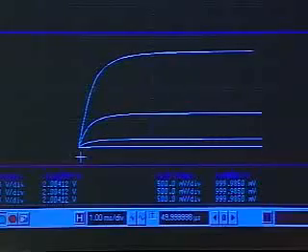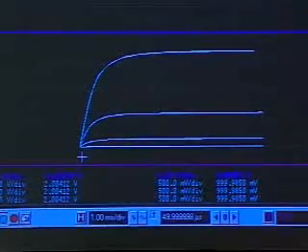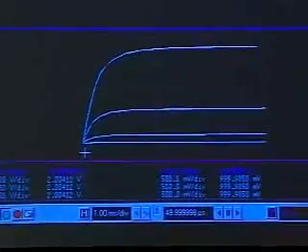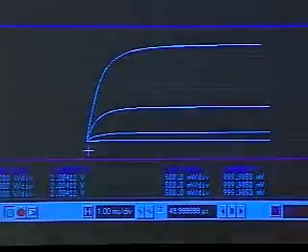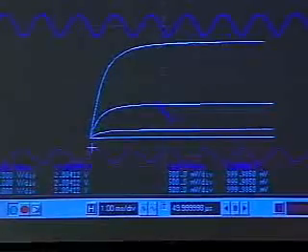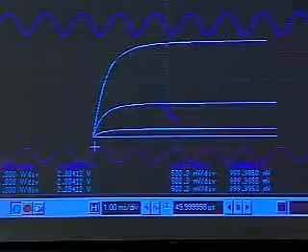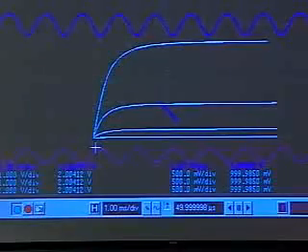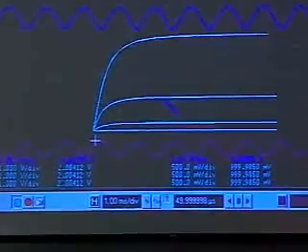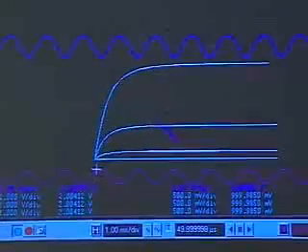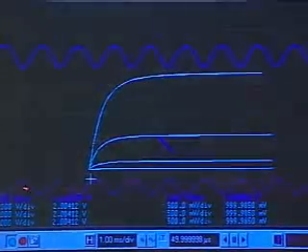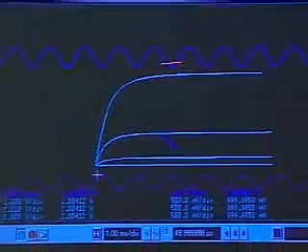Okay. So next what I'll do is show you some more fun stuff. Instead of having just a dot by having a DC voltage, let me apply an input sinusoid. If I apply an input sinusoid at some bias, then I should see an articulation of the corresponding region of the load line corresponding to the input. So as you can see here, the bottom line is my input, and this is my output.